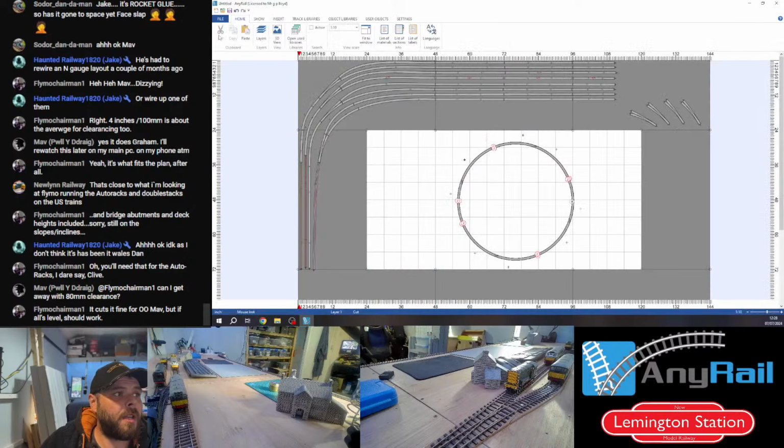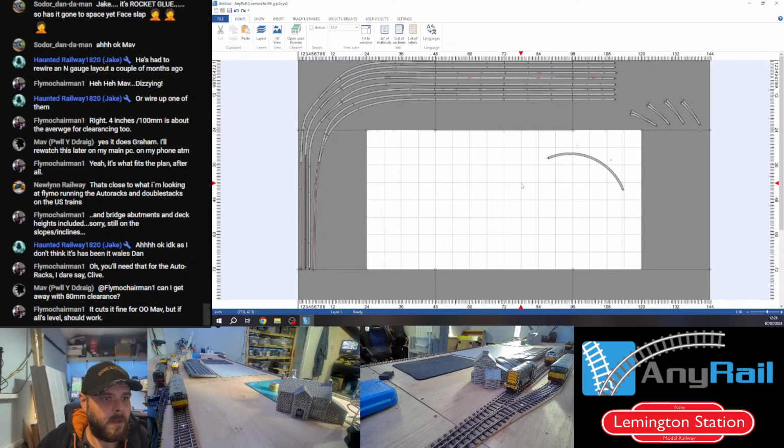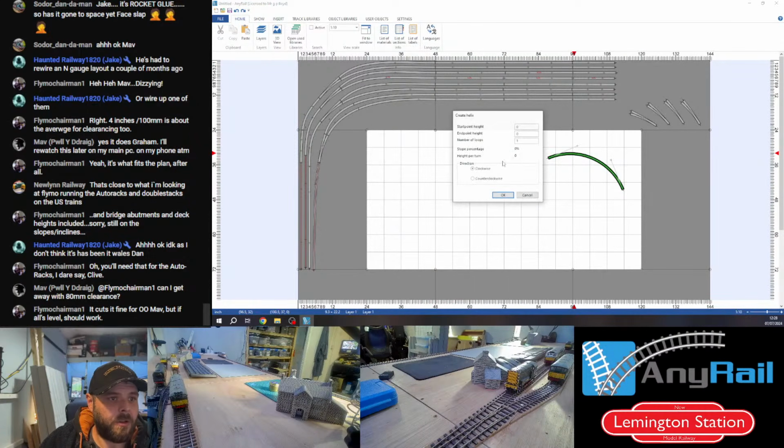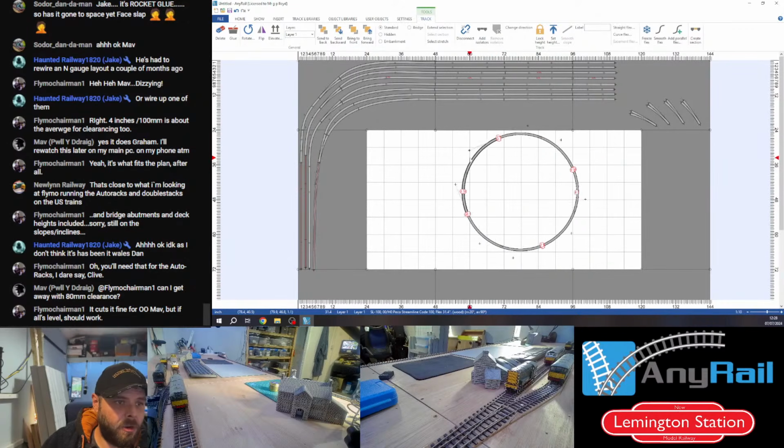So that's why when you go back into this and you create this, you want this number to always have 0.5 on the end of it. So if we're starting at 20 and we're ending at 0, we would probably want 9.5 turns, and then that would give us a 1.7% raise. So then if we bring that up